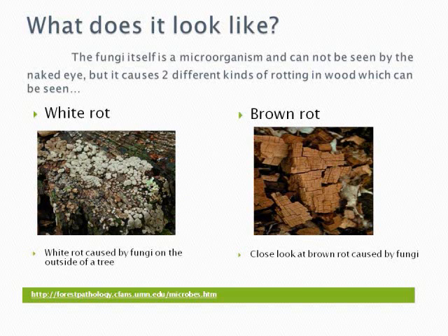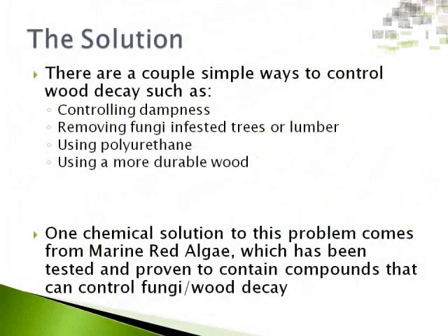On the right you see brown rot, which decomposes cellulose rapidly during initial stages of wood colonization. Considerable loss in strength occurs quickly with brown rot. Brown rot is the most common rot seen in decayed wood inside of buildings. It is also known as dry rot.